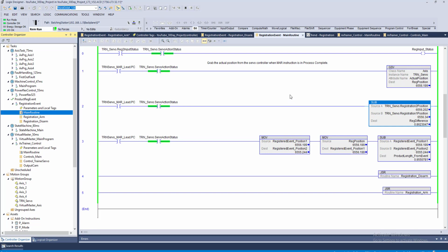So with all that said, hopefully that was helpful, valuable, and gives you a little more information about how registration input is done, how servos interpret the registration input if you're using a positive edge, negative edge, how you use two together, and why it's important to do event-driven.